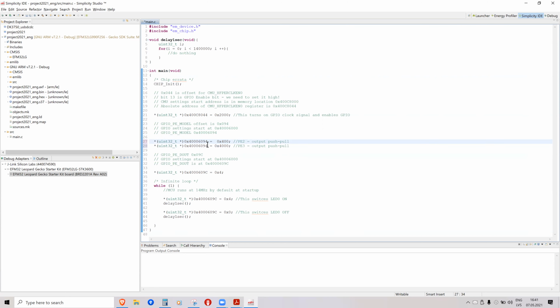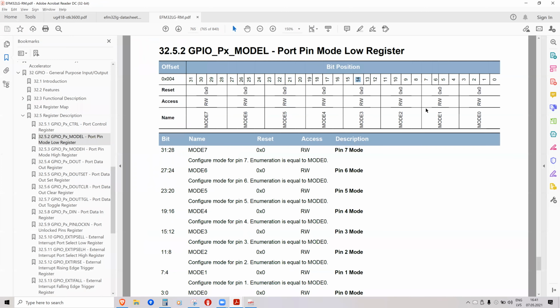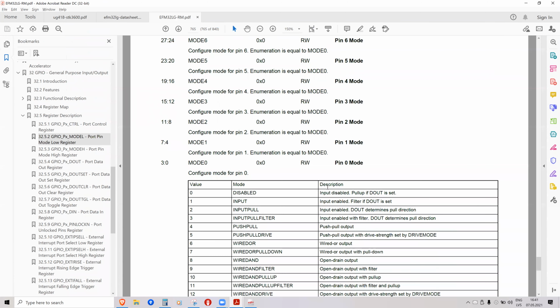So the correct way is that you set both of these ports as outputs in the same line at the same time. So you would need to find a number that you write into this register to set bit number 14 high and bit number 10 high. You cannot set one high while clearing all others because then the mode 0 pin is disabled.